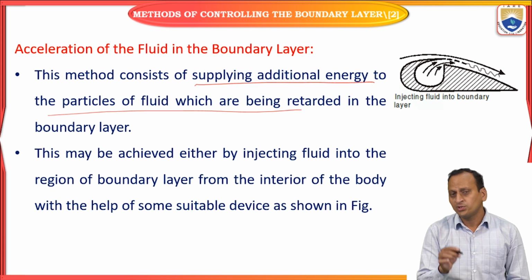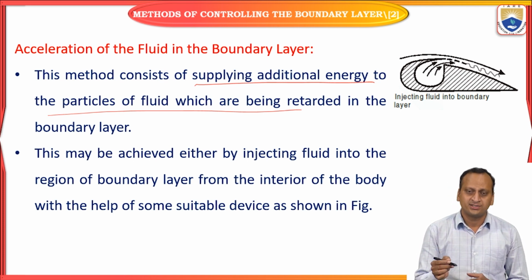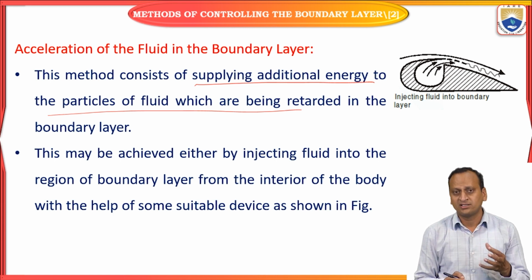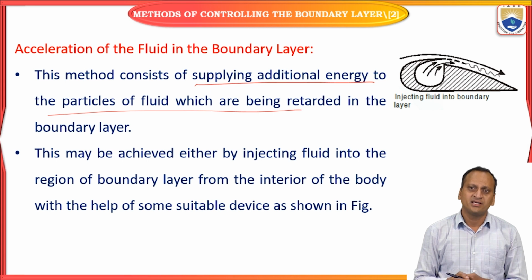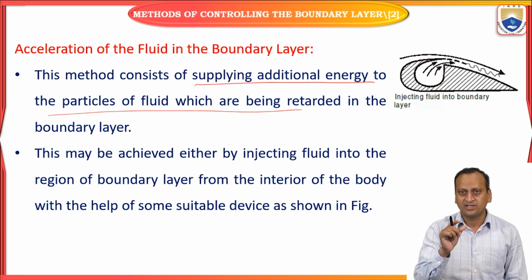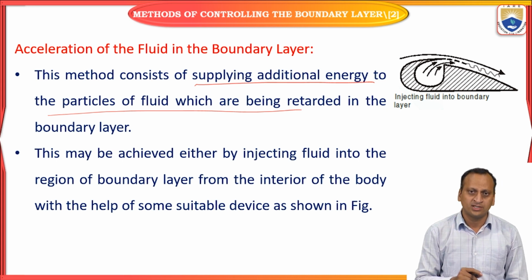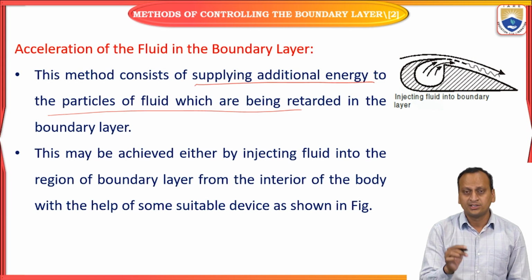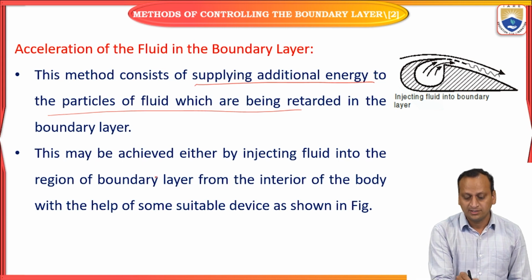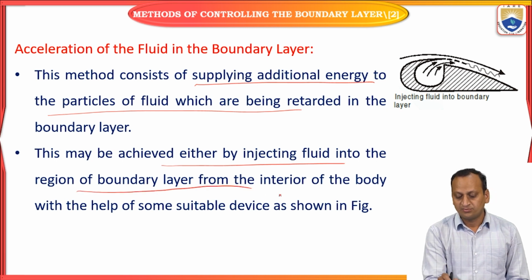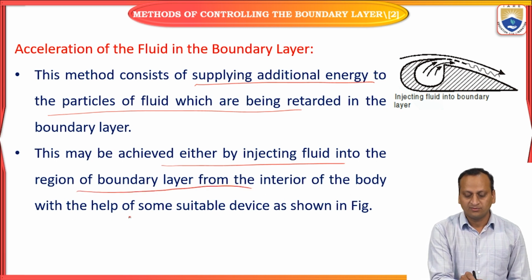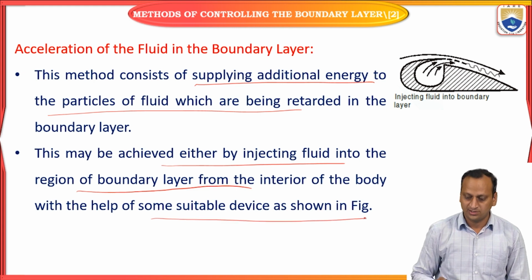So therefore, if you accelerate the lower-energy particles by supplying external energy by some means, they will become accelerated, and there will be less thickness of boundary layer formation, or sometimes it can be removed or eliminated. This may be achieved by injecting a fluid into the region from the interior of the body with the help of some suitable devices.